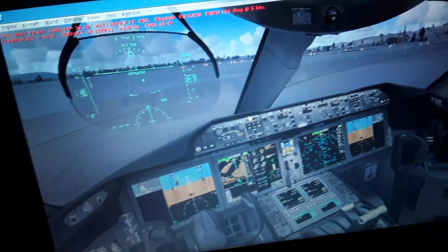You can see also the ILS localizer in the primary flight display. We have the flight director for manual guidance of the aircraft and the autopilot cross for automatic guidance of the aircraft. We have also the flight mode annunciator with the autopilot and the autothrottle vertical navigation mode.